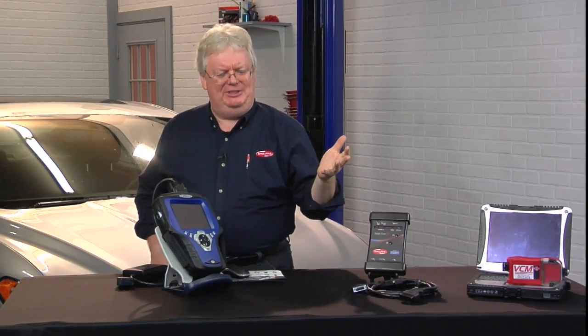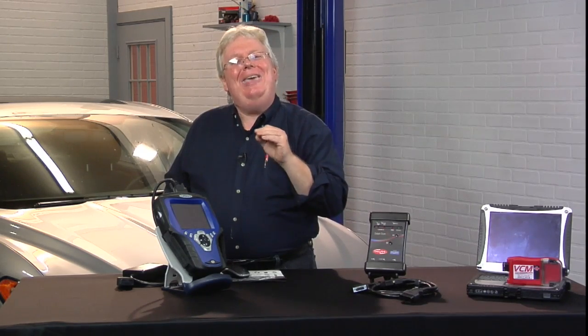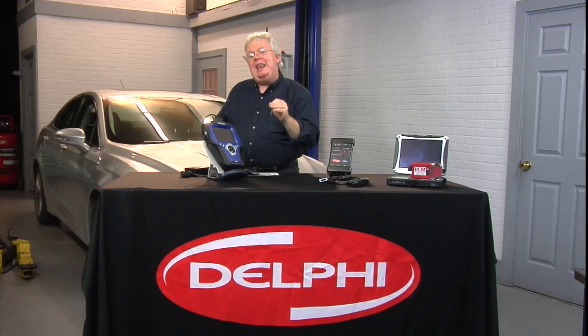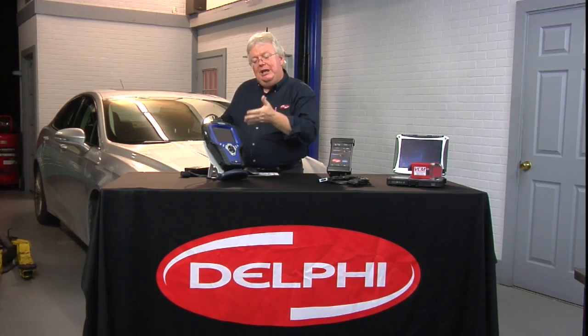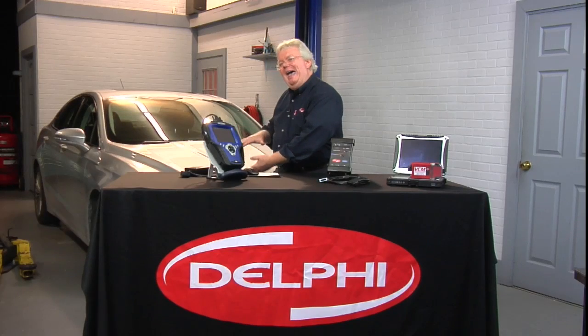Look for the goofy stuff. Somebody's added an aftermarket doohickey under the hood. Sensors fell off. Come unplugged. You set the rack. You see a wheel speed sensor hanging loose. Those kind of things. Look for the low-hanging fruit of something that's abnormal, broke, missing, whatever, burnt, and then go into data parameters and look at live data. Try to see if you can simulate, or I should say replicate the problem. And mode 6 is on down the line from there.